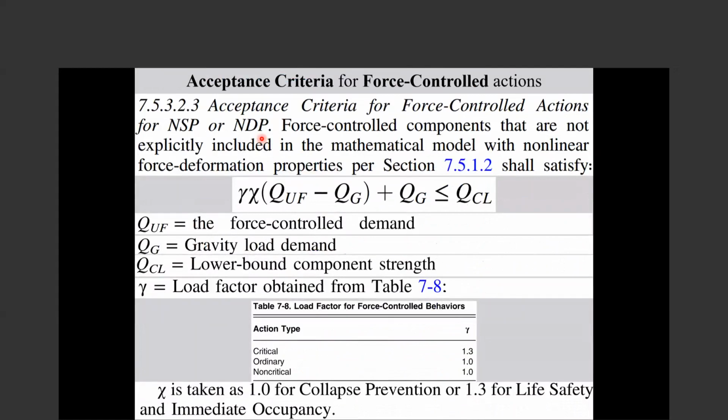It's not important. We don't need a table. Just put the load combination on the element, push the element and this building, and then check the forces and the capacity, the lower bound capacity of that. Previously, the demand was simple. Now, make it more accurate.